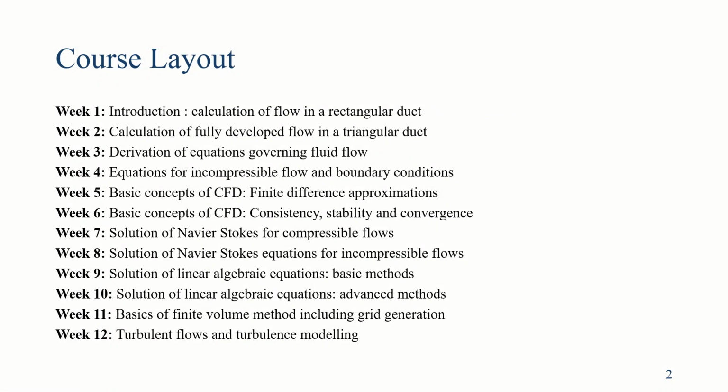We have ease of tackling irregular geometries and ease of grid refinement after solution when we are dealing with unstructured mesh. And third, we have consistently evaluating fluxes in the finite volume method, which means flux conservation across the common faces of adjacent cells.